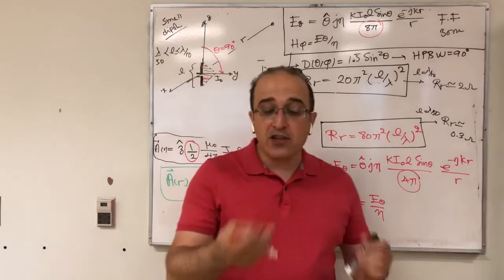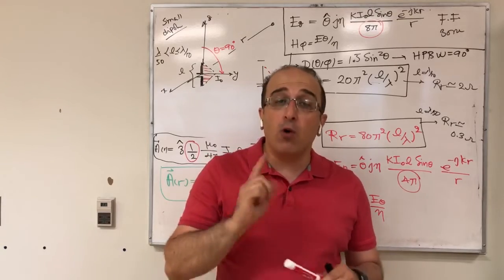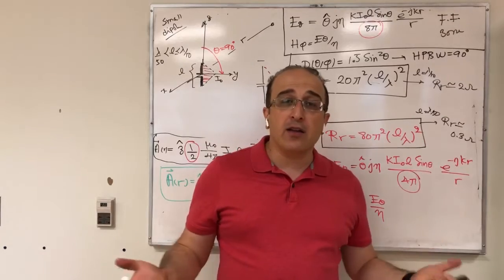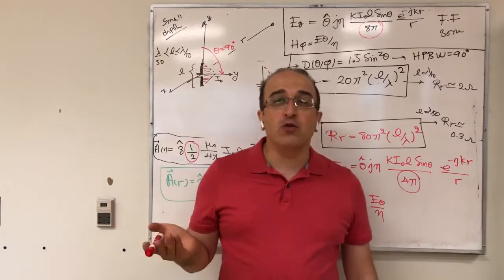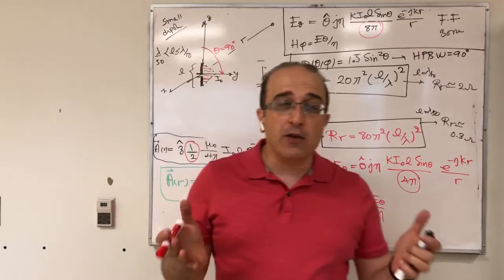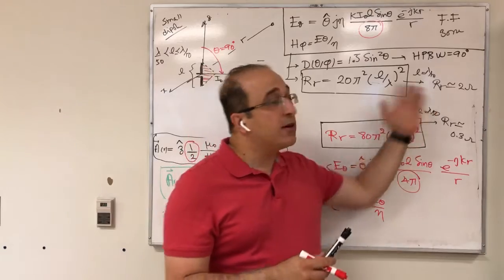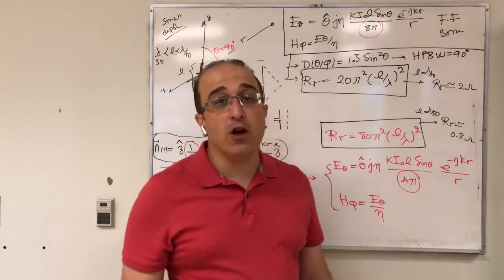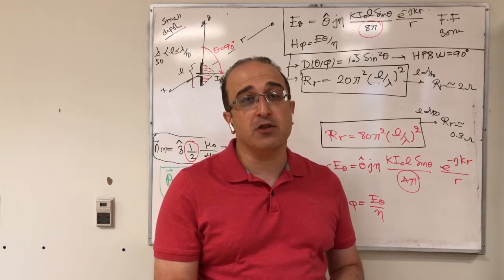Now, the natural next step is to increase the length even more, because even with 2 ohm, you see it's not a very good radiation resistance. As you see, when we go to a longer antenna, for example a half-wavelength dipole antenna, this value gets closer to 70-something ohm, which is much better when you compare it to the 50 ohm characteristic impedance of the transmission line.